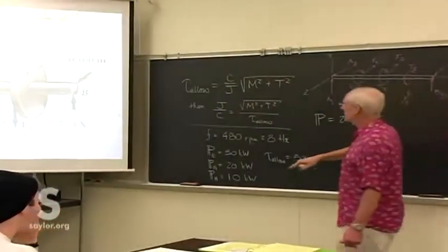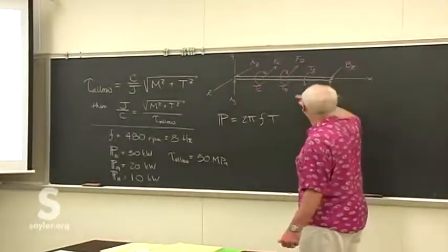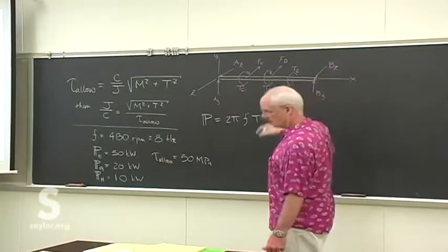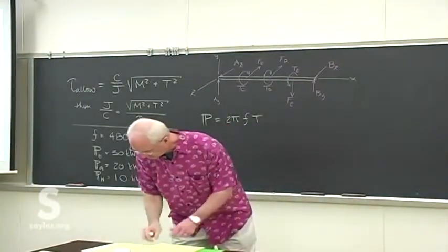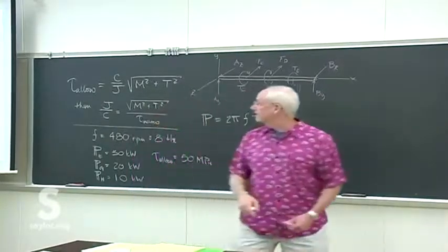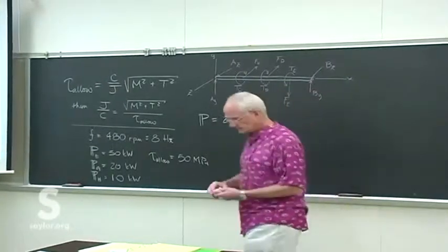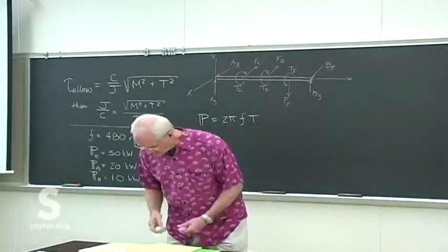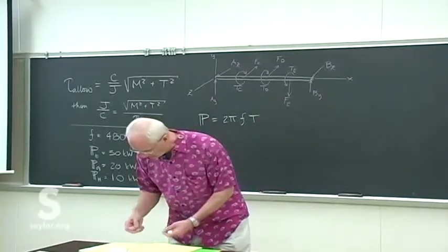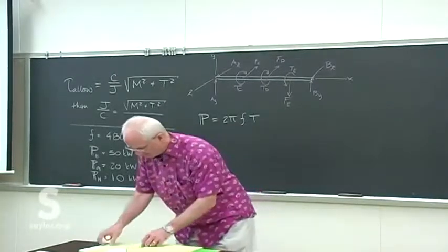And that's then how this 3.73 was figured out. Know the torque at E, know the radius at E, and then find the force at E, because we know the radius of that gear. That's given there, the 0.16 meters. Okay, so we can do that for each of the pieces. I won't force you to do it on this one. You can on the next one, but these values come to be